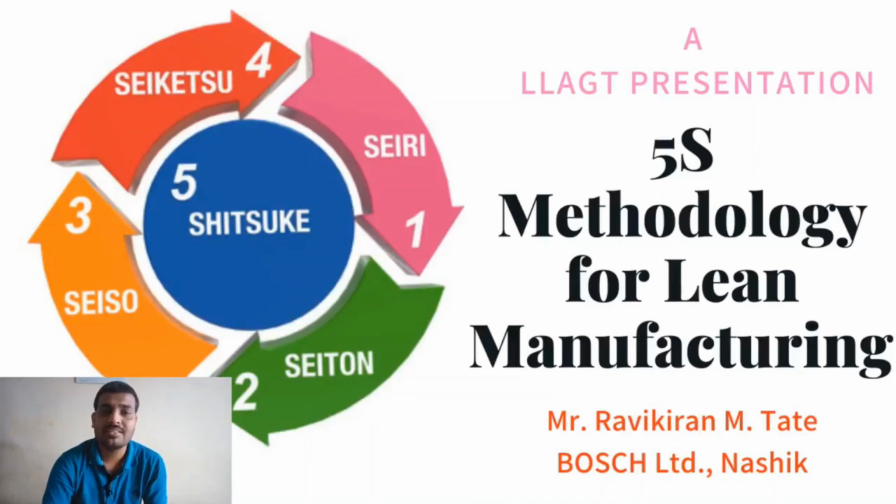The third phase is shine. Shine is nothing but cleaning. This cleaning is generally understood as inspection or control. It will help you with early detection of wear and tear of the equipment. Then 4S stands for standardize. This standardization is required for eliminating the possibility of returning to the original position. All the activities done in 1S, 2S and 3S have to be made standard, so that it will not come back to its original position.